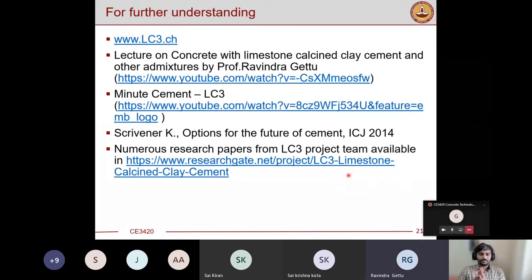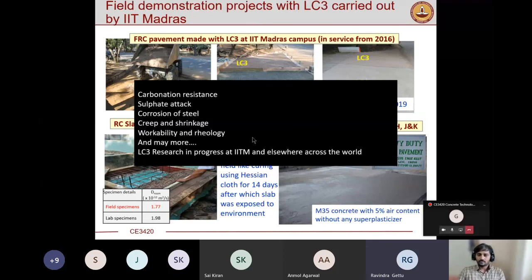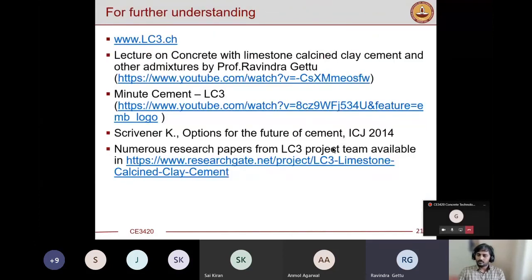Thank you, Yuvraj. There are some comments which have come in the chat. One is the question: when you have the graphs, like for the compressive strength, you are showing bars. Are these bars showing the variability? Is this the standard deviation? Yeah, the bars are showing the variability of a number of samples, right? You can't test one cube. So basically we test 3 or 6 cubes. Those show the difference between the samples.